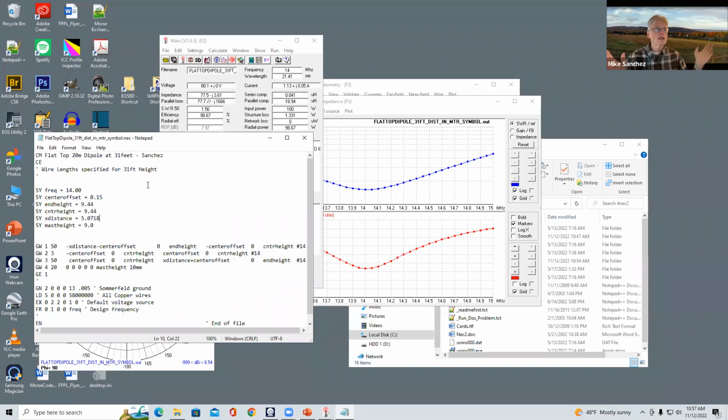I cut the wire exactly as the simulation said, put it on the mast and pushed everything up. And ladies and gentlemen, perhaps partly because I'm using RG8X, it was perfect. The minimum was right where I wanted, perfectly in the middle of the band. And since then, I have validated all manner of SWR responses relative to my reality.